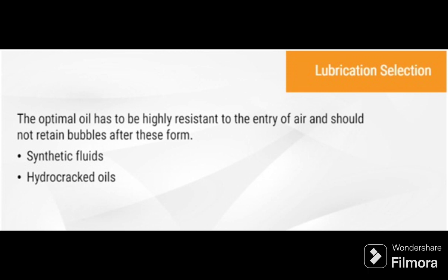In lubrication selection, the optimal oil has to be highly resistant to the entry of air and should not retain bubbles after these form. The oils that best comply with this model are synthetic fluids and hydrocracked oils.